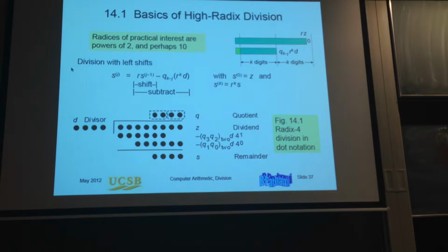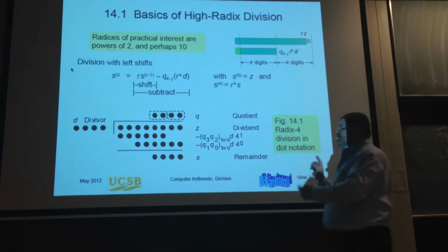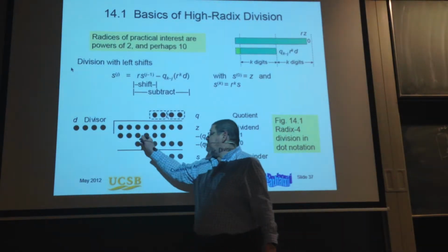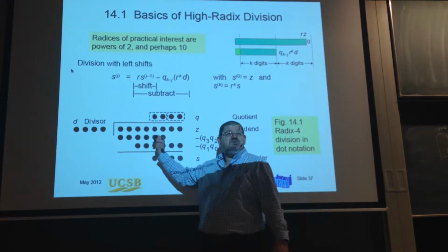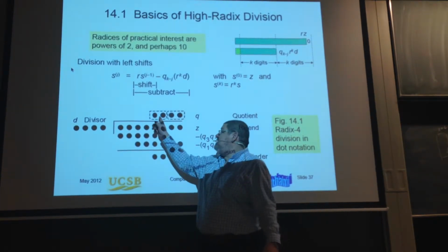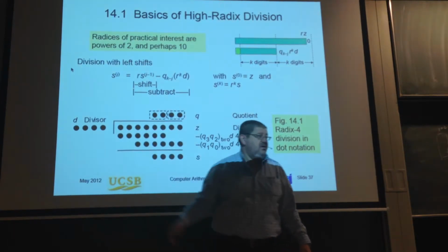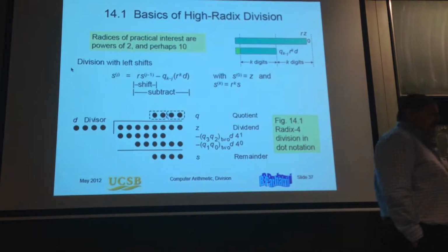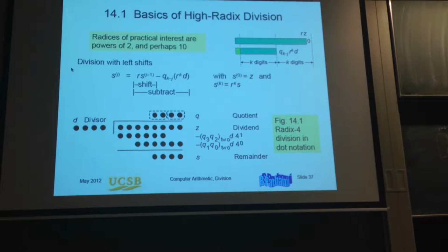It's not because the operand is wider. You see I changed from a 4-bit addition to a 6-bit addition. It's not a big deal. The problem is how to guess this value. I can use the straightforward, brute force approach, and say try with 3, with 2, with 1, and 0, but this will end up killing all the advantage.